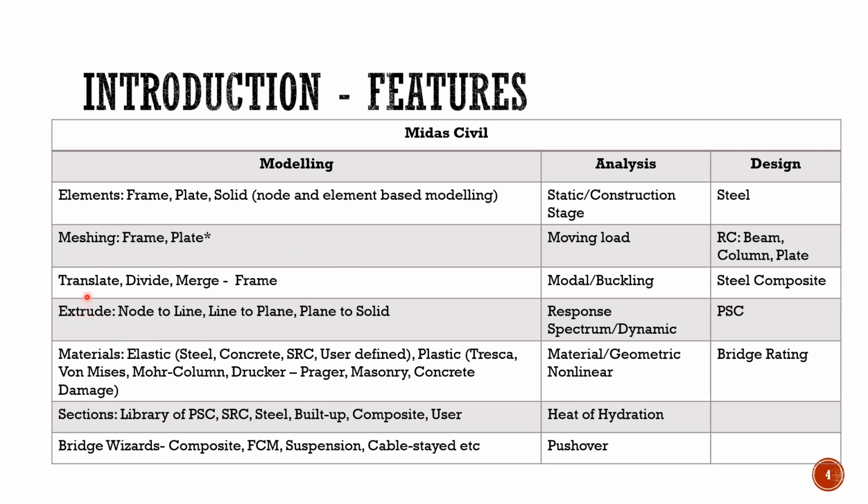Further, we have CAD based tools such as translate, divide, merge to generate complex geometry with ease for bridge structures. Further, we have the extrude tool that enables us to create node to line, line to plane and plane to solid elements, which is again very useful for creating irregular geometry.